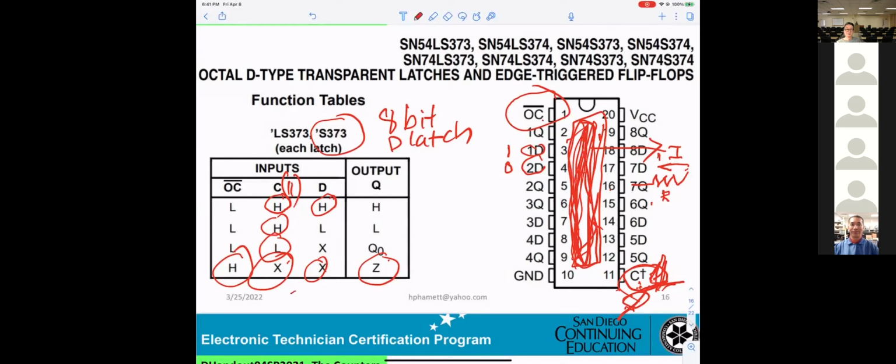However, on the address, only one IC is supposed to be used. And also the data on the data bus, only one IC can send the data out or receive the data. But there are too many memories inside, so they have to get the circuitry to control, allowing only one IC to be on.